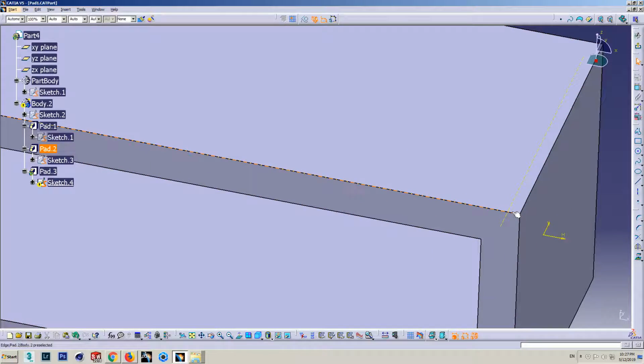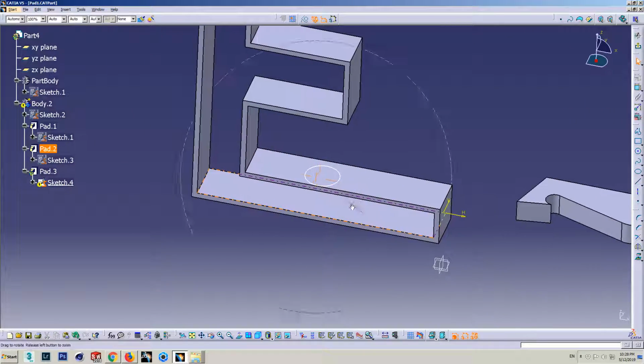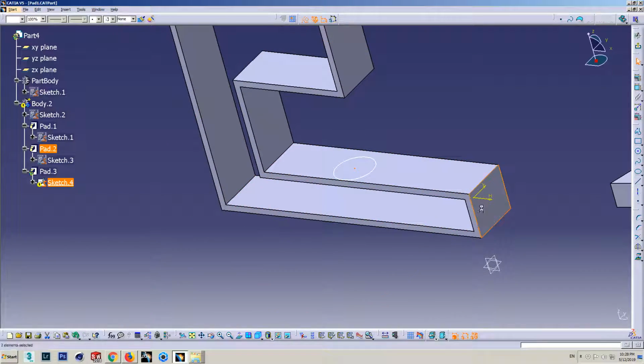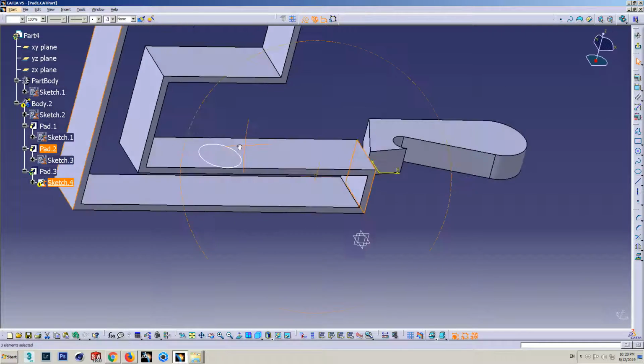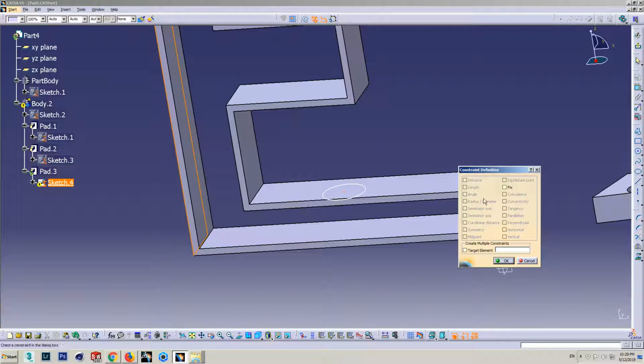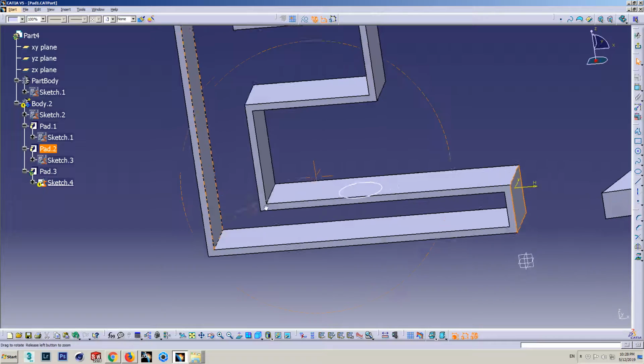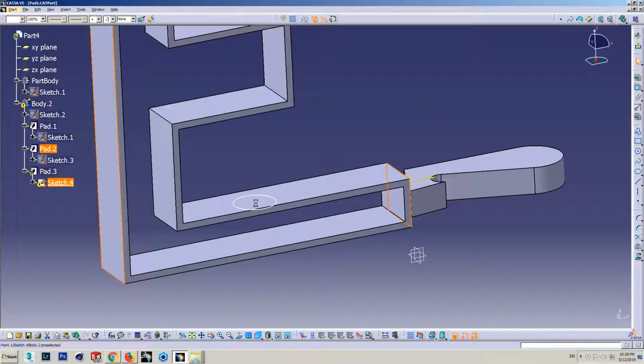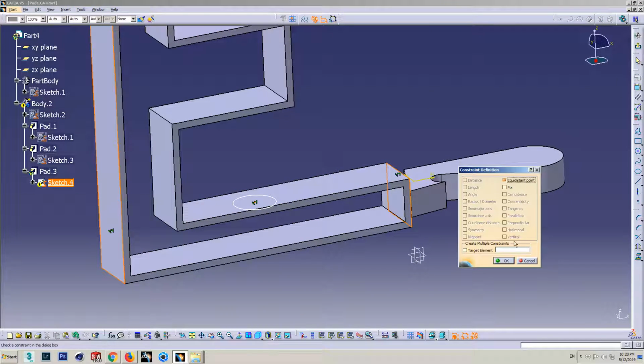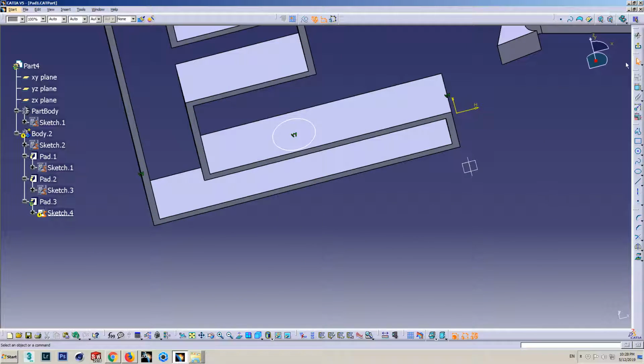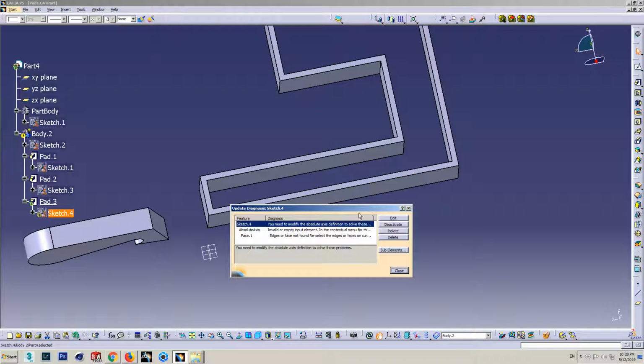As you can see here, there's a gap, and this plane is no longer usable as a reference. So I only have to delete those, and I can reposition these to those other faces. And lastly the circle, equidistant, in order to position it according to the new geometry.